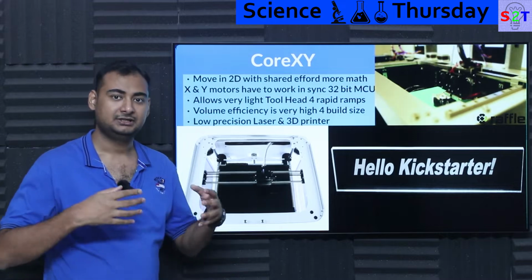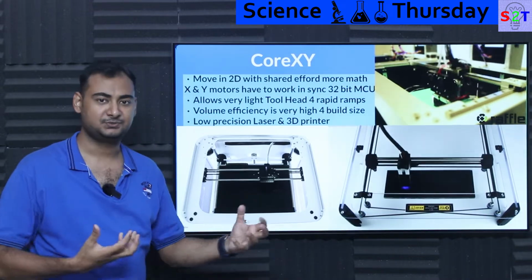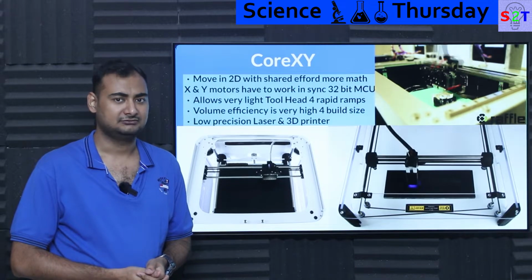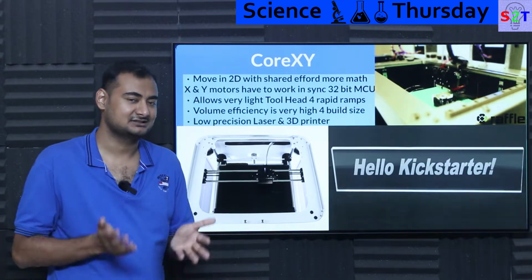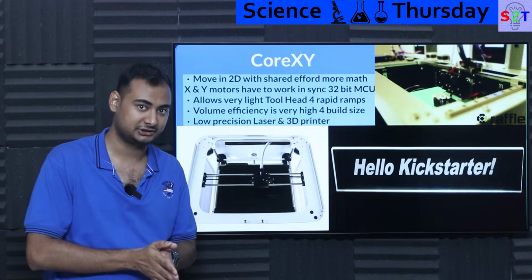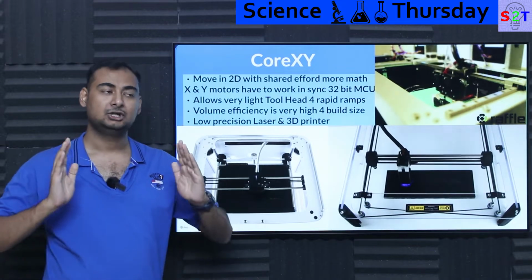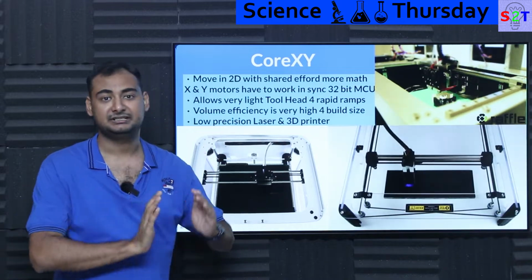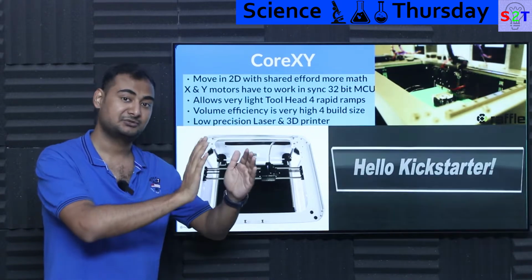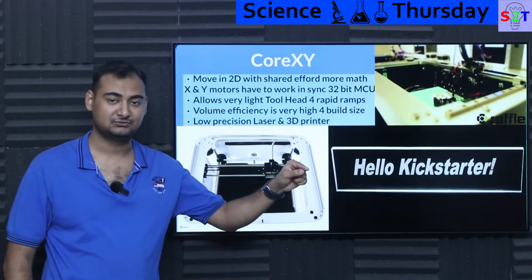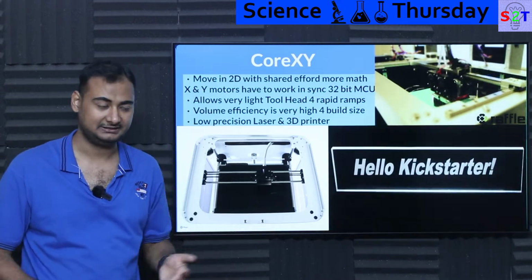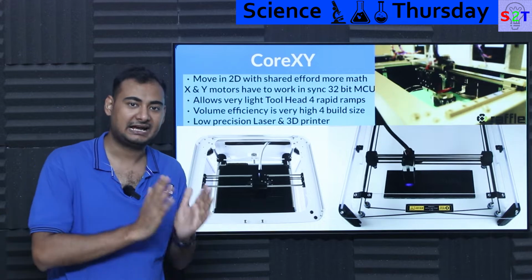Now you have to understand this. You may think, okay, I'm just going to increase the speed by increasing the motor capacity. Yes, it will not work that way. Like, why? Well, here's the deal. In principle, that should work, but there is a law of physics known as inertia, meaning if you have a heavy object, no matter how much horsepower you put into it, it will take a certain amount of time to get up to speed, and then a certain amount of time to come down from the speed. So basically, when you want it to accelerate and decelerate, it will have a maximum G loading. No matter what you do, it has a limitation to it.